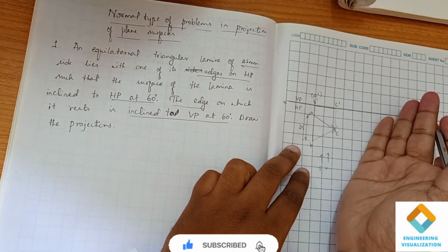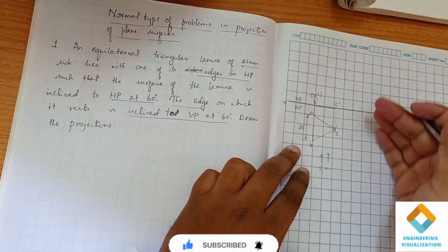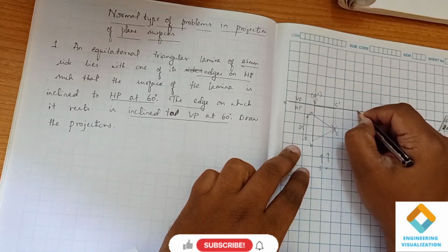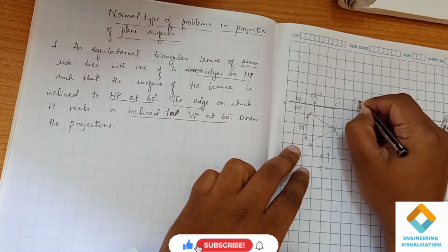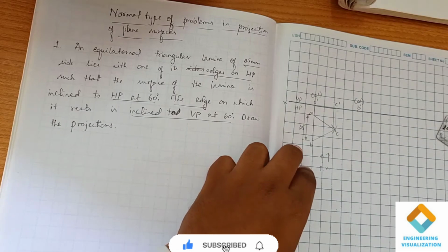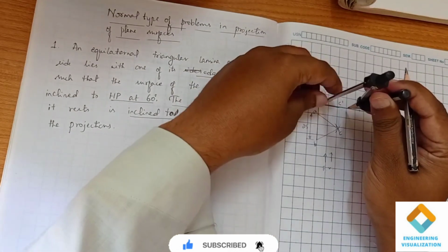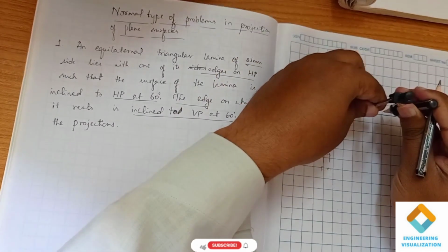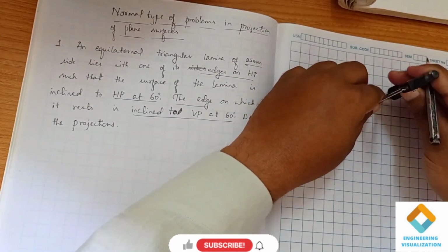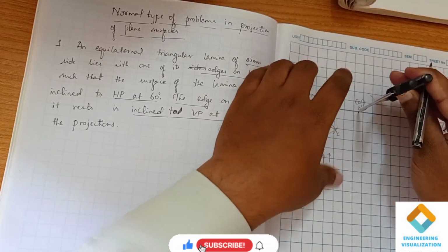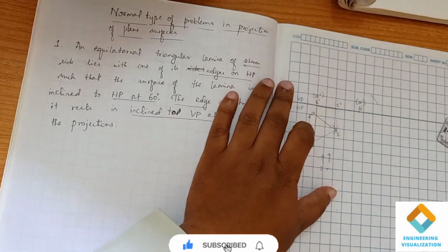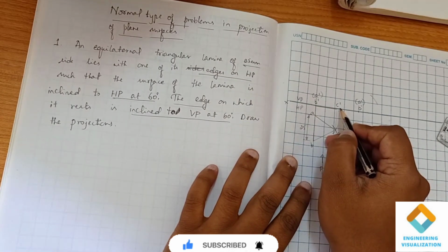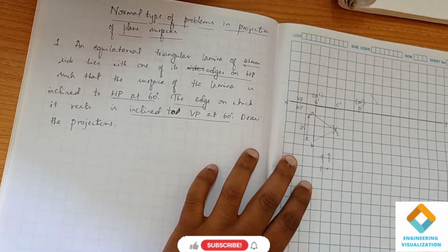I am going to show the first front view, then I will draw the inclined top view. For that purpose, first I will write this B dash and A dash. This is our reference point. After that I will measure this length, that is B dash C dash, and cut the arc. We have already cut the arc, but we know that we have to incline this B dash C dash by an angle of 60 degrees.